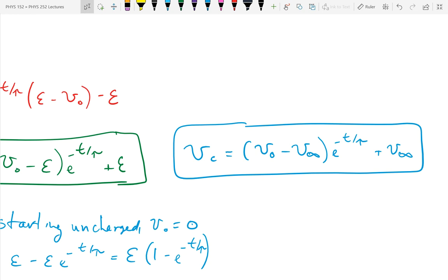So we would have gotten this equation if we decided to start it without the EMF. And so we would have had just one term instead of three terms, right? Because we technically have three terms that I factored. And so we would have had to come back and do it again if you had made the other decision. But it's a quicker derivation the other way because you don't have as many items to worry about, right? There's no reason to do a U substitution if you didn't have the EMF in there. So it's a quicker derivation, but you have to come back and do this one anyway. So that's the equation for the voltage when you're charging or discharging the capacitor.